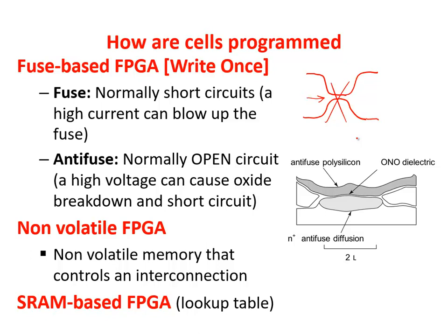But there are also other possibilities which are reversible, and they are based on memories which control the interconnections. They can be non-volatile memories that control the interconnections, a sort of ROM or PROM that can be programmed, so that you can change the status of, for example, a pass transistor, which is interconnecting two different blocks.